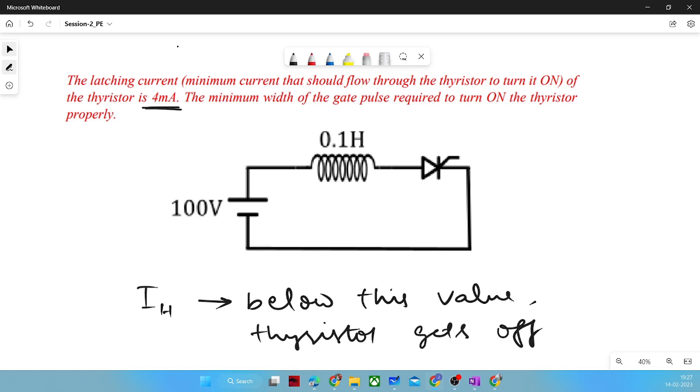But in large motor industrial applications, where we generate electricity using high powers in the level of megawatts, like 2 or 3 megawatt, thyristors become handy because the thyristor is a very rugged device with very high voltage blocking and current conduction capability.